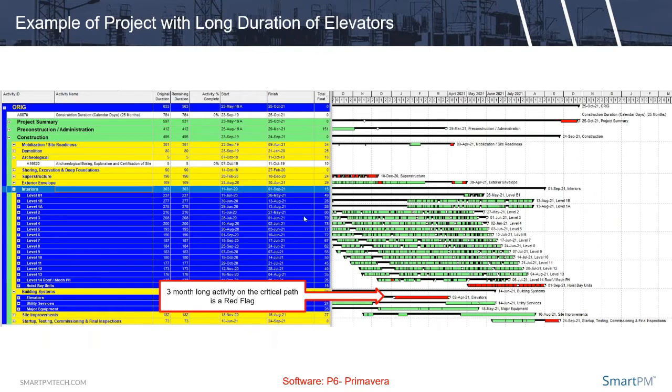Here's an example of a different schedule where we have this critical path going through the superstructure. As we know, we'd like to see it go through the building and the interior trades, but we don't. We see it in elevators. So this is basically telling me that in order to effectively manage my job, I'm going to need to make sure that the superstructure goes up on time, that the elevators get placed on time, that we finish up tying up the roof on time, and then we work on those units where the man hoist is, which doesn't seem right. That seems odd. It seems like way too few things that can drive a job, and it just doesn't make sense.